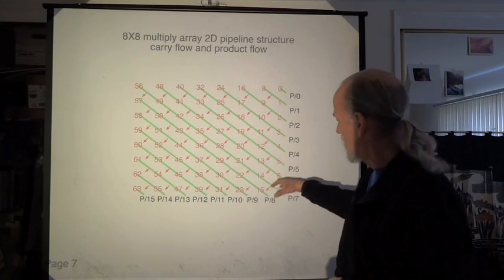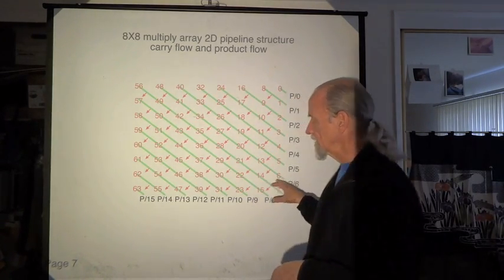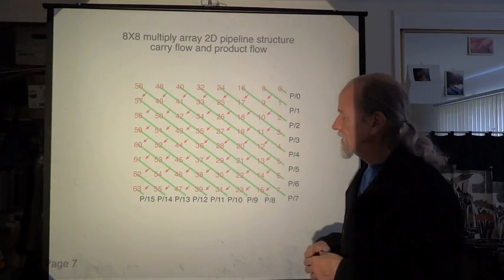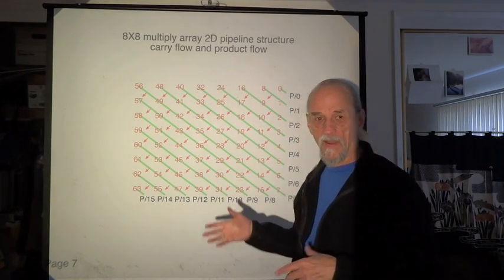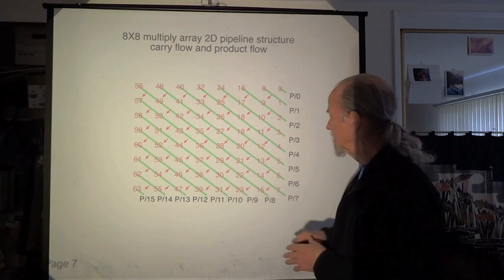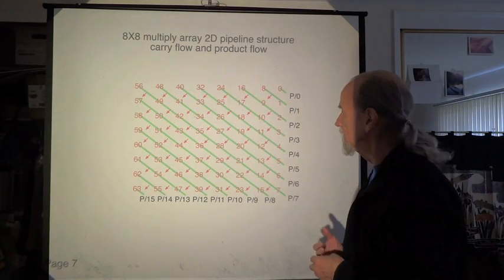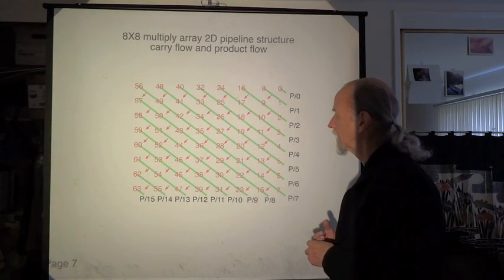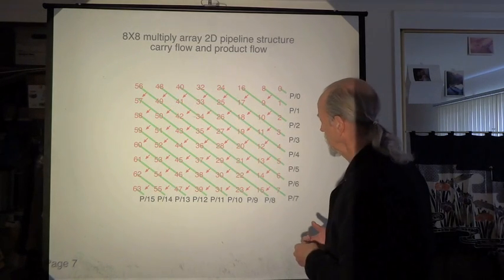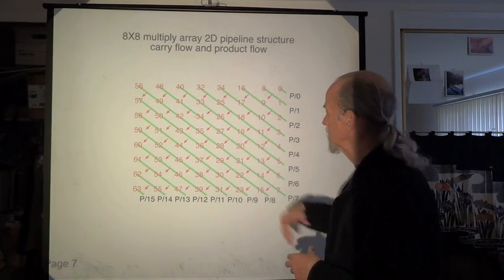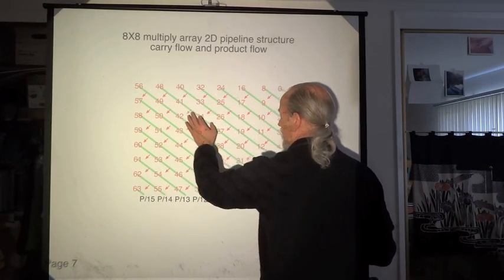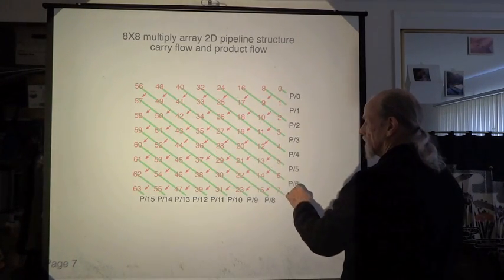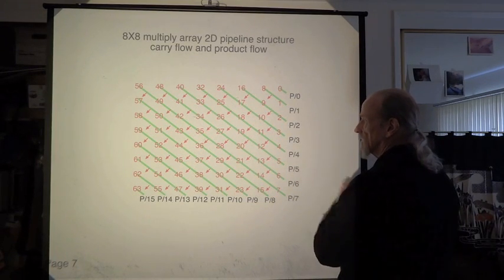And by the way, we have a linear numbering here, 1 to 63 of the array, because iVerilog doesn't do two-dimensional arrays, and we have to do our own two-dimensional addressing. So we have a single-dimension array representing our two-dimensional array. So that's why the numbers are this way. So anyway, now partial products 48, 41, 43, 27 are all available simultaneously to be added.